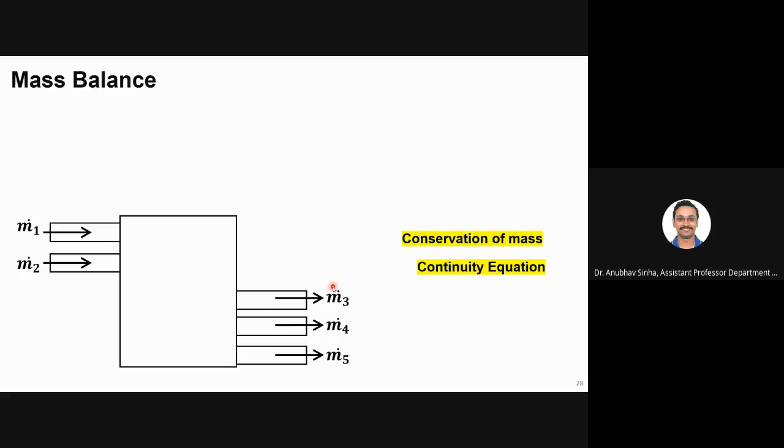Now, for an open system, we need to define a control volume. Remember we discussed in the initial classes that we need to define a suitable geometry for the control volume. So what will be the most suitable option for the control volume? Anyone want to guess? Can I make a control volume like this? Can I take this shape or not? No, sir. Anyone else? I think I can take this shape. You can define a control volume of any arbitrary shape that you like, but it will make your analysis difficult. So we can take it, but we will not take it.